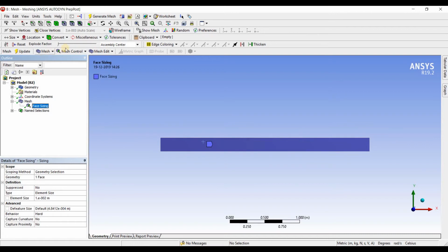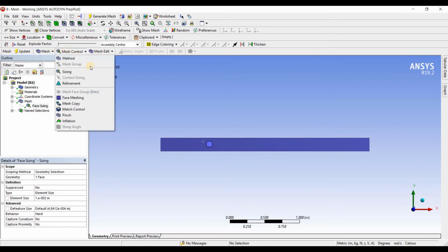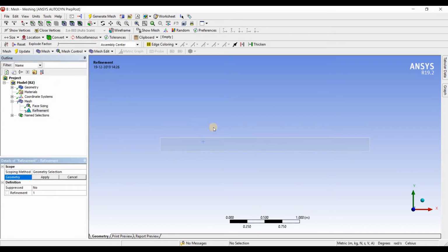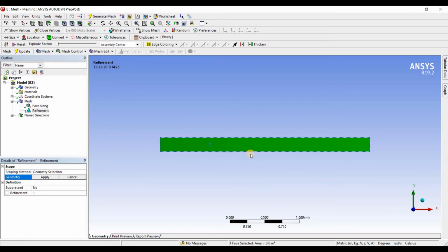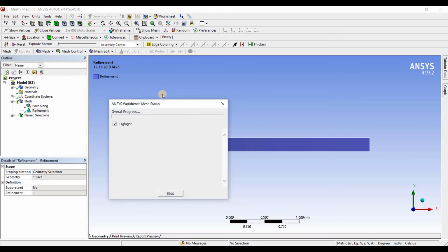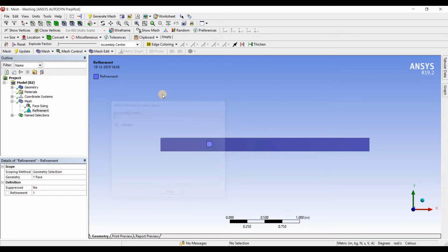Okay. The next mesh control I want to talk about is refinement. Refinement gives an optimal mesh which is often non-uniform, finer in areas where large variations occur from point to point, and coarser in regions with relatively little change. I just want to see how refinement will increase the number of cells in a grid.